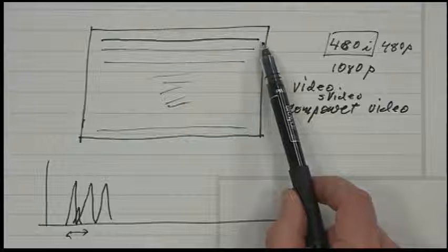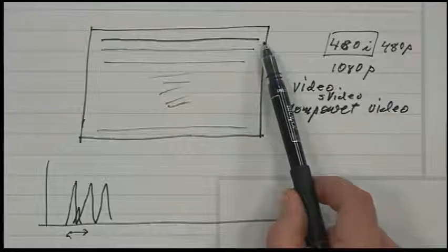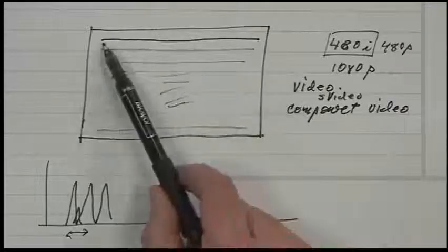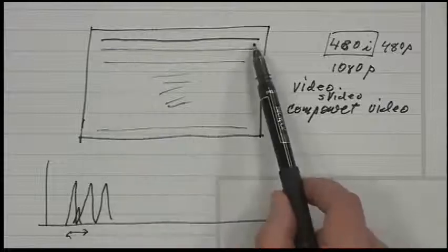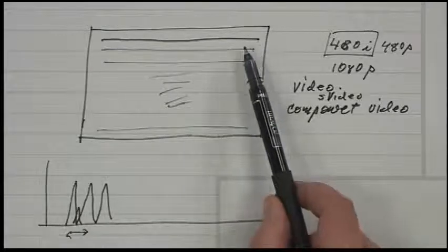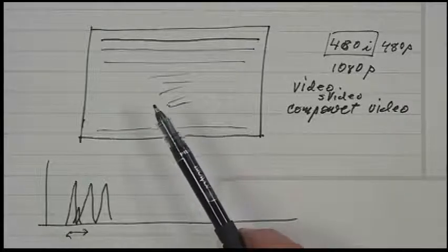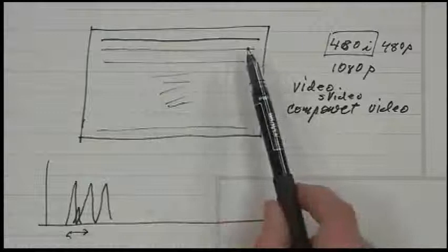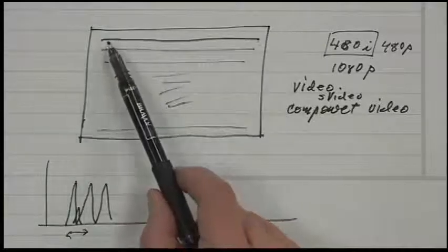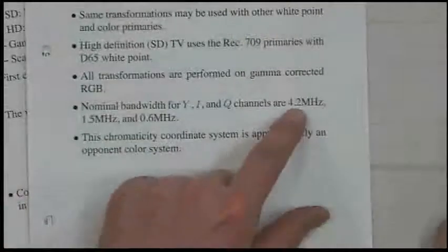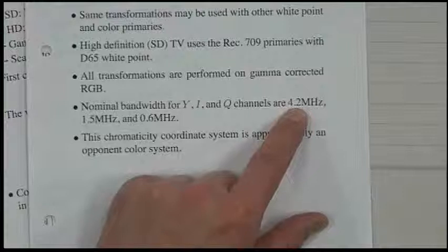So knowing the bandwidth of the amplifier tells you the spatial bandwidth in terms of cycles per line. If you take the cycles per line and multiply by 2, I'd have to think about it a little bit, you get the equivalent Nyquist rate. That specifies the equivalent number of samples on a line. So these megahertz numbers have an absolute meaning: megahertz equates directly to samples per line in terms of resolution.